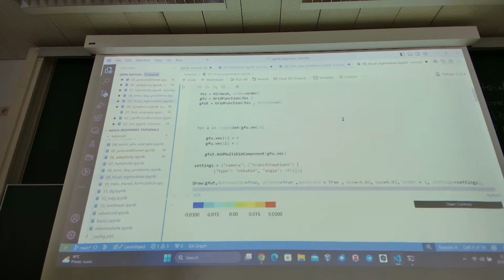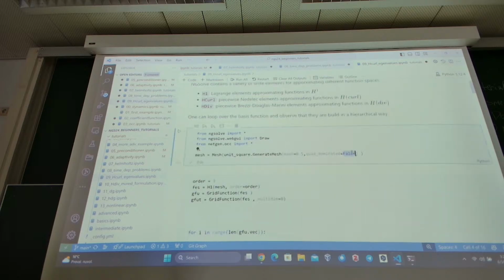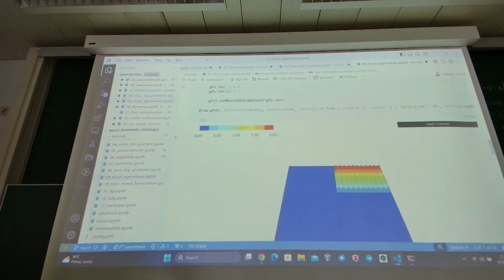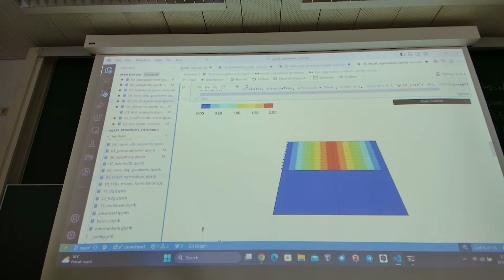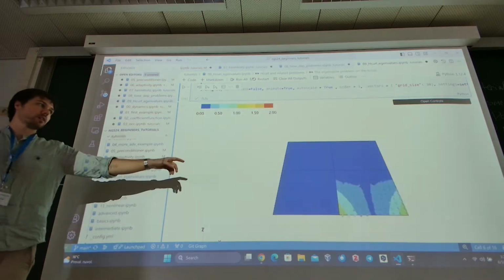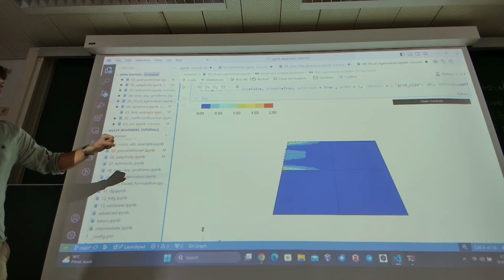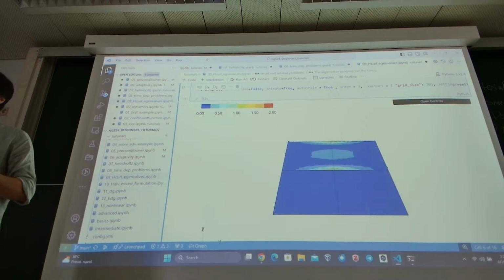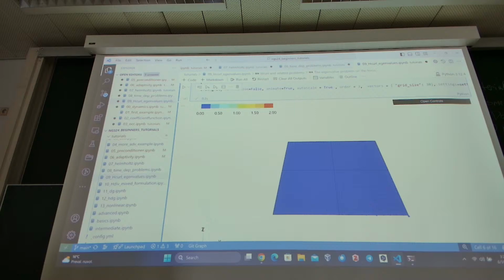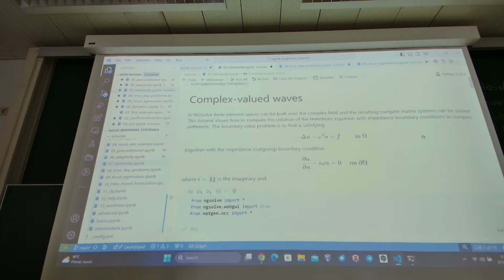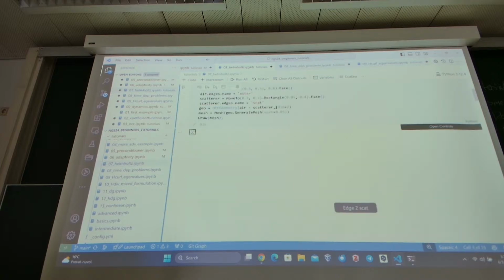If you do this for quads and you make max h much lower, do you then get quads? Not necessarily. In the square, I think that you can still always have quads. Inside other complicated shapes, you not necessarily have quads. When you want to have a square quad mesh, use make structured mesh, because it's an academic approach. Okay. And can I see if maybe here we can see where it is?